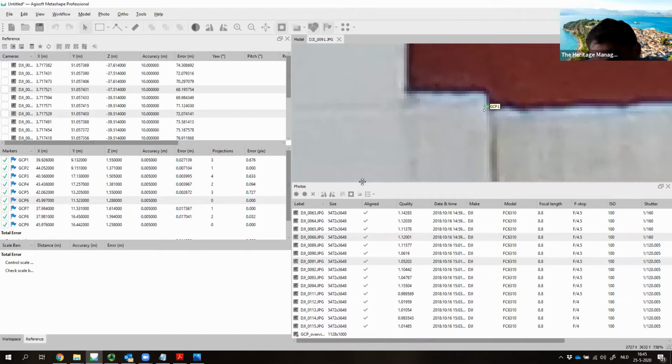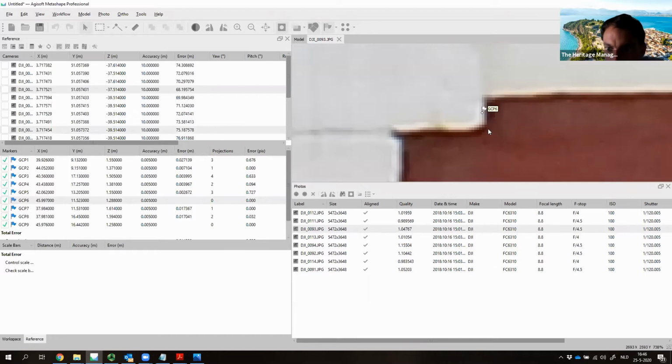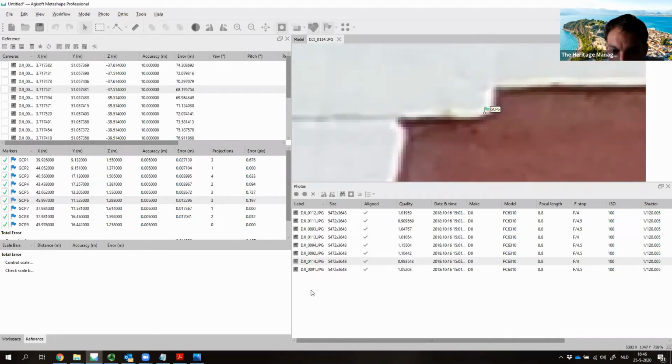The only reason why you have to select them all is that it will make sure that if you select a photo, the photo of the ground control point is actually apparent there. So now I only have a few photos from the entire population of photos, and I can just select a certain photo, and you see that GCP6 is automatically used for panning and zooming.